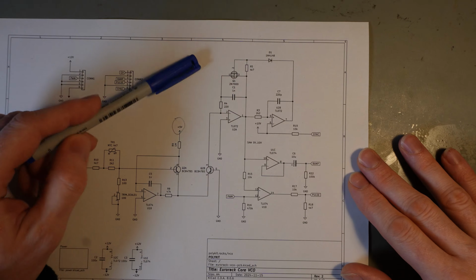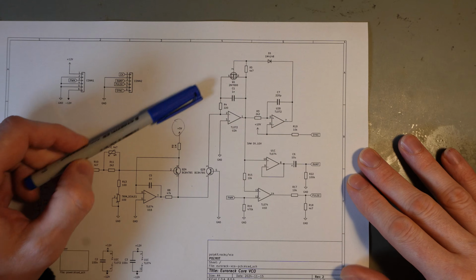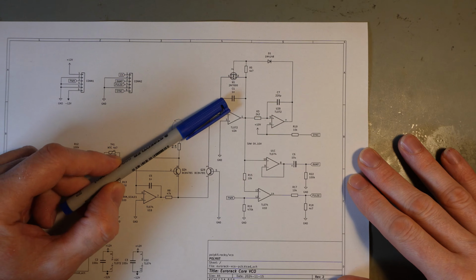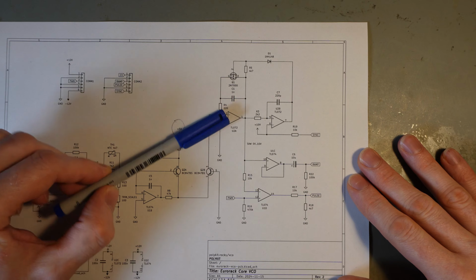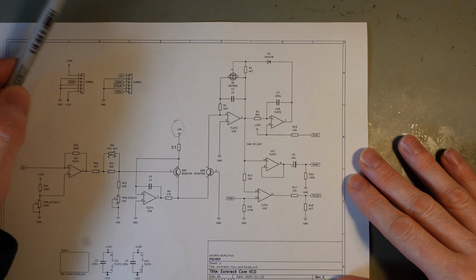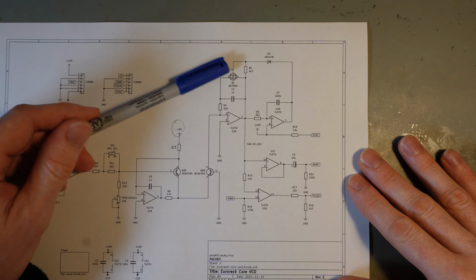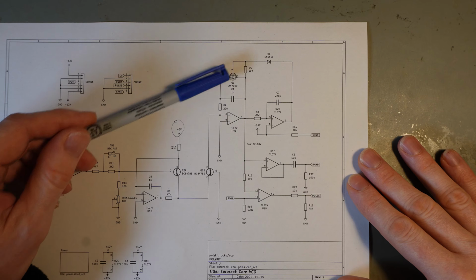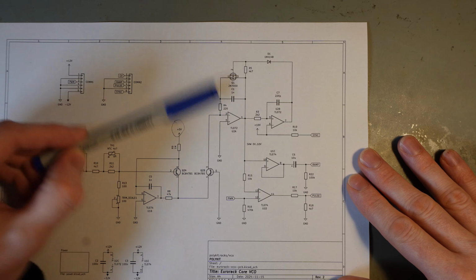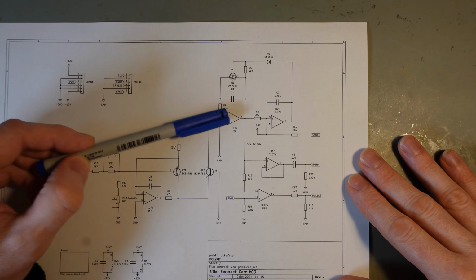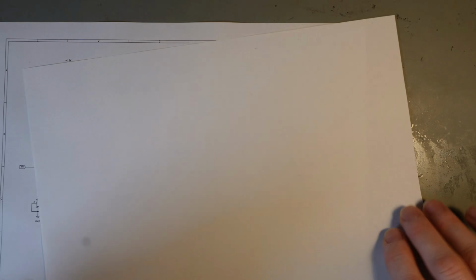So this here is the oscillator core. And how this works is actually very simple. We have this capacitor here, and this is charged. And when it's reaching a certain threshold voltage, then it is shorted out with this transistor here. So there's a comparator, and when you reach a certain threshold, then this is shorted out and the cycle starts over again. So this looks basically something like this.